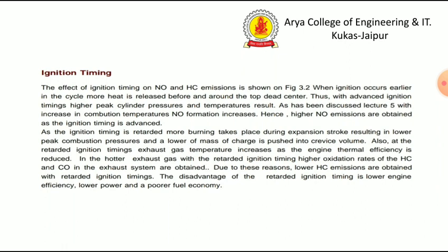As the ignition timing is retarded, more burning takes place during the expansion stroke, resulting in lower peak combustion pressures, and a lower mass of charge is pushed into the crevice volume. Also, at retarded ignition timing, exhaust gas temperature increases as the engine thermal efficiency is reduced.